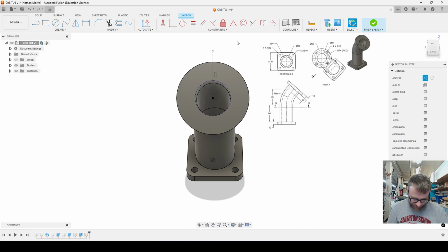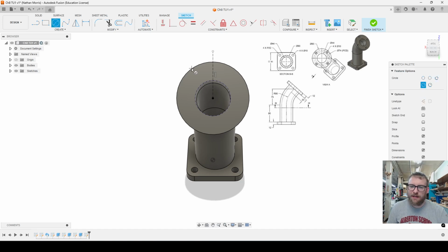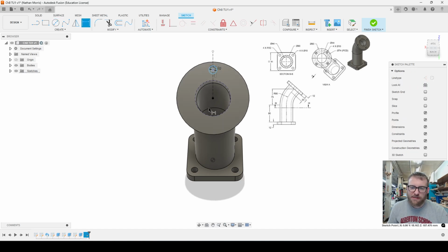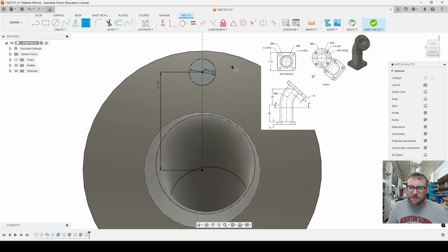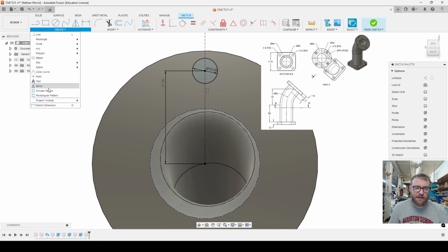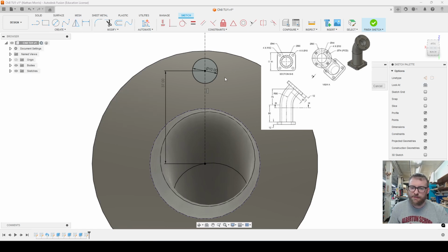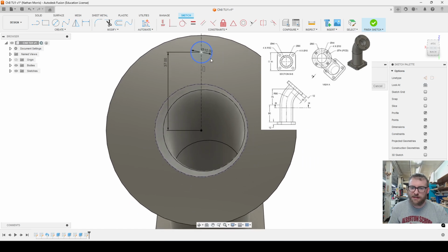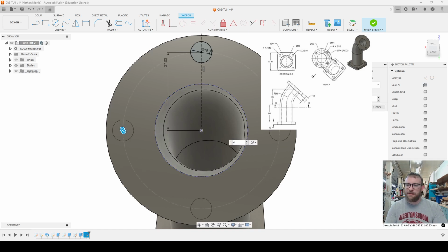And then we're going to make a circle that is 10 millimeters in diameter, centered 37 millimeters from the origin. So in chapter 9, we talk about what if we had made this a 3D feature already and then did a circular array, but for now we are going to use the circular pattern in the sketch toolbox. So we're going to just actually select this circle, select the center point, and we want 4 of these.